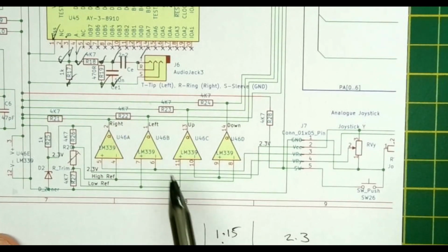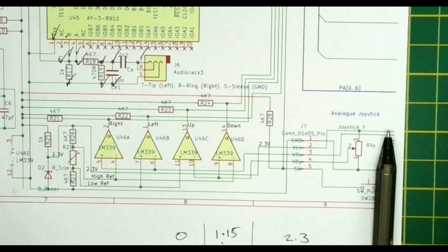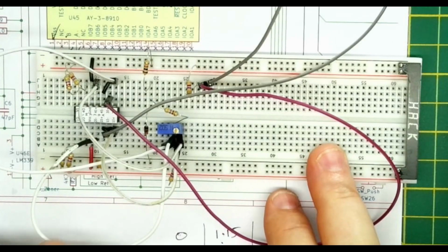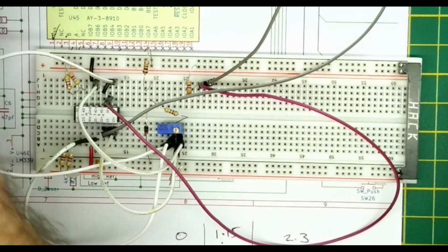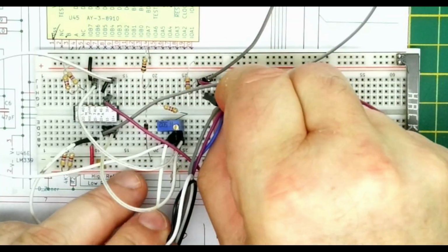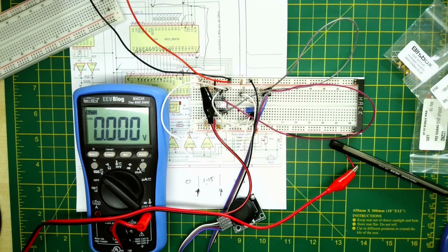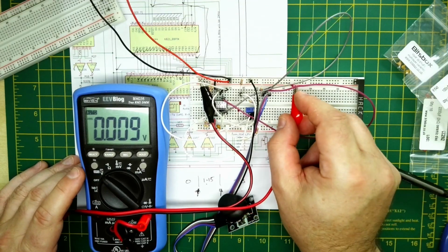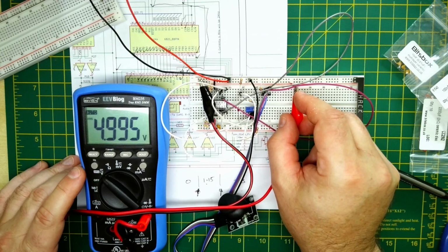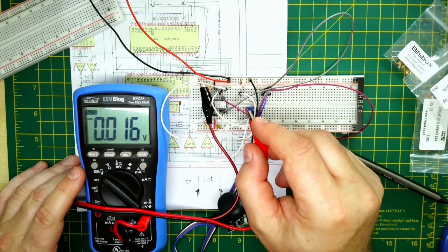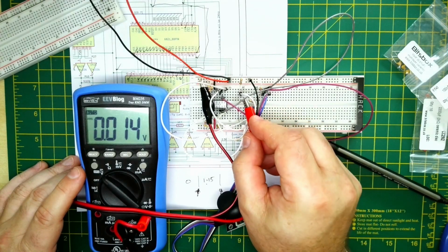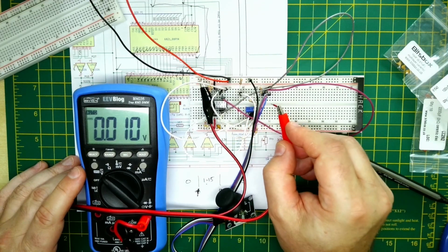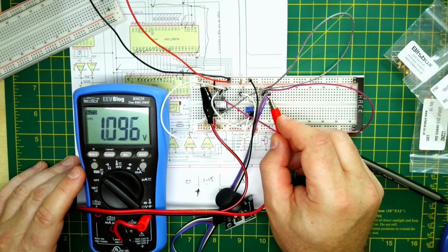It took a little bit of experimenting to get this working, and what I have here is the circuit that I got working. It's a little bit messy because it's in prototyping mode. I'll connect the joystick to here. Okay, I've hooked up the circuit and I've now got the power on, which is just under 5 volts. If I take a feed off the Zener diode output, that's about 2.3 volts, which is what's going into the VCC line of the joystick.